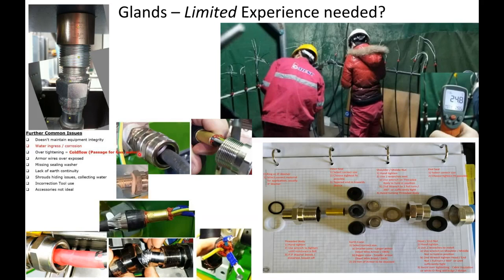So when we look at glanding, I've come across many projects where mechanical personnel are the management. They don't understand that this is a mechanical device to ensure the electrical safety of the equipment and the cable. If it is not installed correctly, people can be electrocuted. It can cause a potential source of ignition.